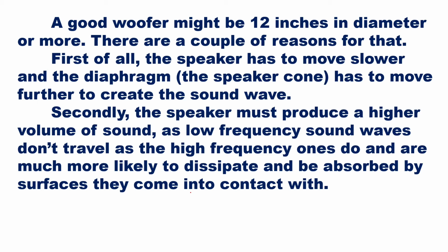So here, the general idea is that a woofer will have a larger size. Its diaphragm will be around 12-inch in diameter for a better woofer. Secondly, its connection between the voice coil and the dome outside will be very loose so that any vibration in the voice coil will be converted to the diaphragm and then it will be converted into sound waves.